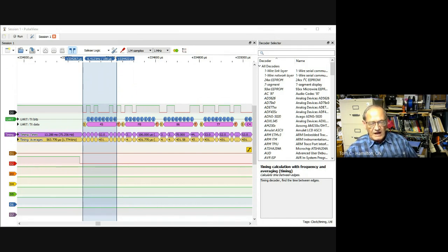And looking at the logic analyzer, it just looked like a mess. The binary patterns weren't consistent with what it ought to look like as a digital UART signal. But when I put this same signal on one channel of my scope, it became immediately clear what was wrong, because then I could see the analog voltages associated with these digital signals.